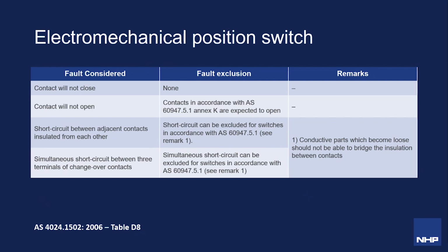Contacts will not open. This one does have a potential fault exclusion. We can consider that the likelihood of the contacts not opening on demand isn't significant enough to warrant monitoring for, provided that the contacts are in accordance with AS 60947.5.1 Annex K. If you're not familiar with the standard, and I will forgive you, this is the one that describes the requirements for electromechanical control circuit devices.